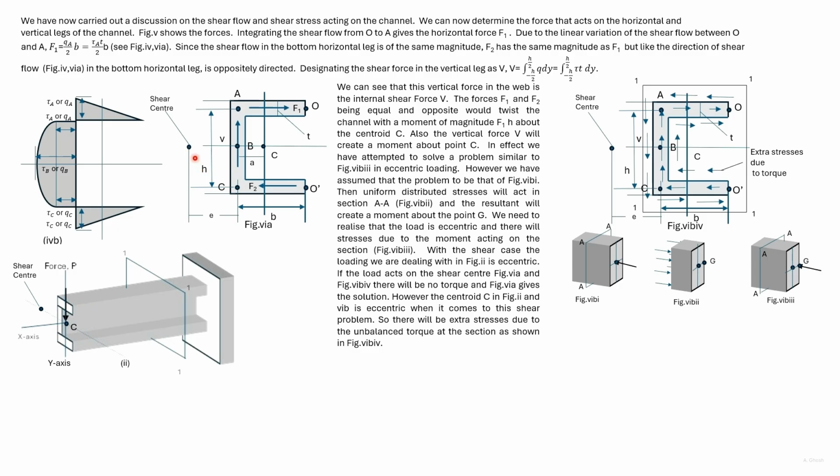That separate point is called the shear center. So this load is eccentric like this load, and this section will be subjected to both shear and torque.